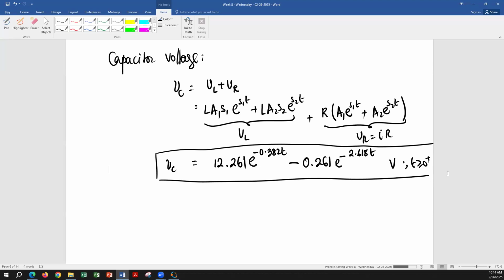It does not really matter which damping type. However, you have to look at the circuit given to you after t greater than 0 when it becomes natural, and from that circuit you decide how to write the equation when finding the values of A1 and A2.